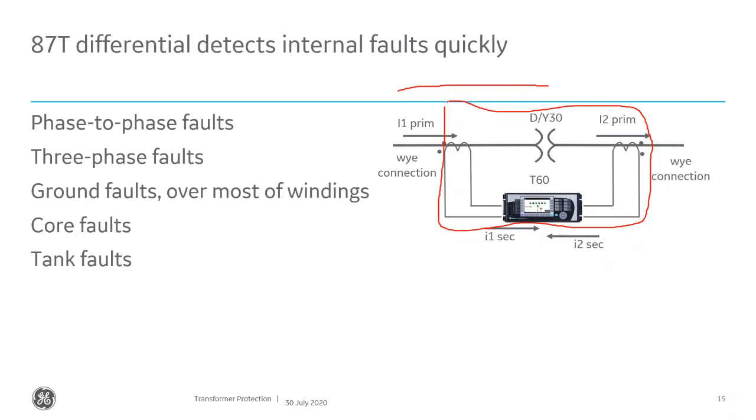It's also why I have these time current characteristic curves where we stack these elements up. So that time coordination will slow things down. There's no intentional delay that we have to add on a transformer differential because it has a defined zone of protection, which is, as I've shown in this box here, from that CT on the left to that CT on the right.